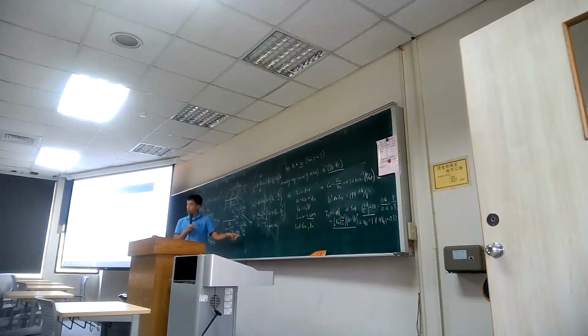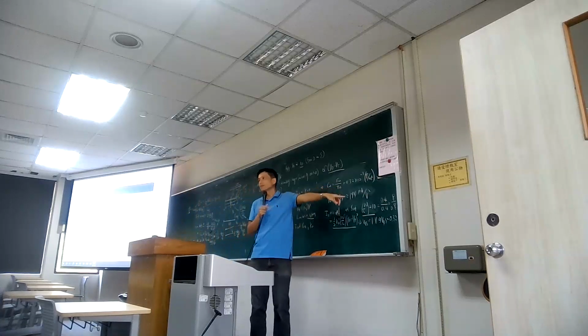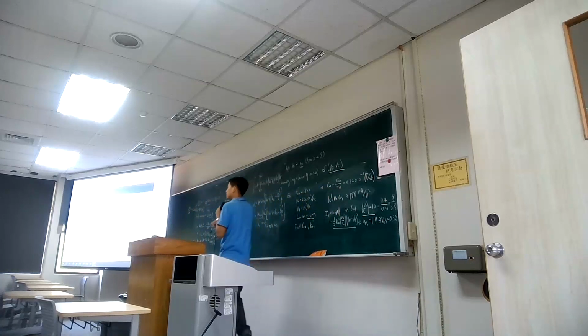Here, C_ox equals epsilon_ox over T_ox, since we have multiplied this because it is the thickness of your oxide layer, right? So if you want to increase the current, how do we do it? We want to reduce the thickness, or increase epsilon. If you are working with oxide layers, epsilon is a physical property, you cannot change it, right? So you shift the dimension of the thickness. So that's the reason you can see why we want to use a thin oxide layer.